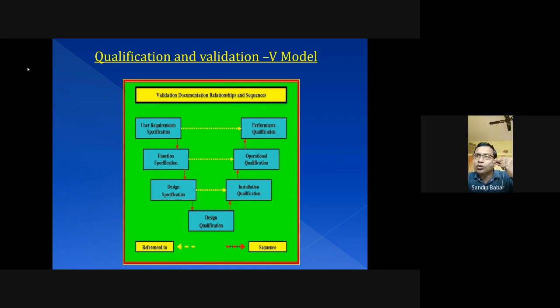So we will pressurize the vessel up to 2 bar and give a limit of 0.1 bar as the acceptance limit. Suppose if the leakage is more than 0.1 bar, then the pressure hold test fails. But the automation of that pressure hold test has 5 to 6 steps; directly it will not start. Consider that we are doing the pressure hold test in an automated fermenter or bioreactor. There will be one sequence, that pressure hold test.